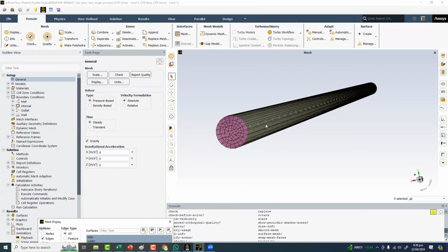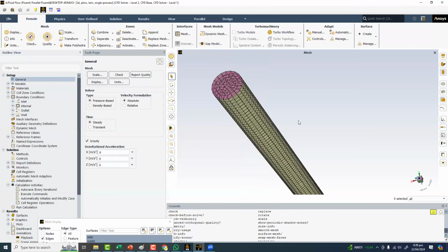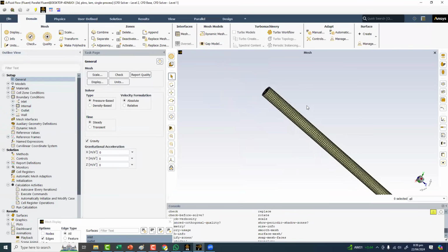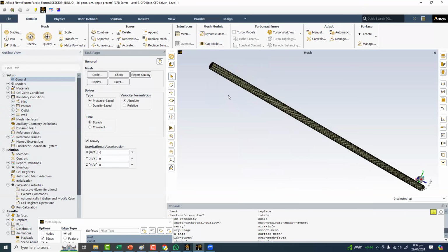But for multi-phase flows, if the gravity is vertical, it is influential. Let's say you are solving a problem with a vertical or inclined pipe. In that case, we have to include the gravitational effects. Like for a vertical pipe or an inclined pipe, we have to include the gravity effects. In that case, this is necessary.